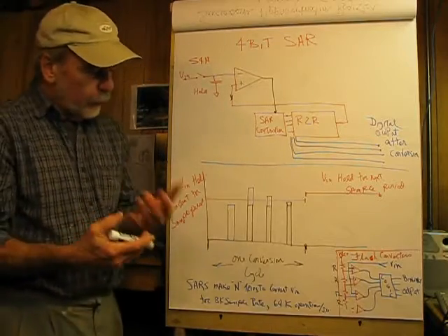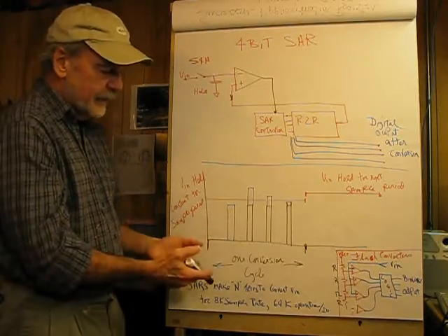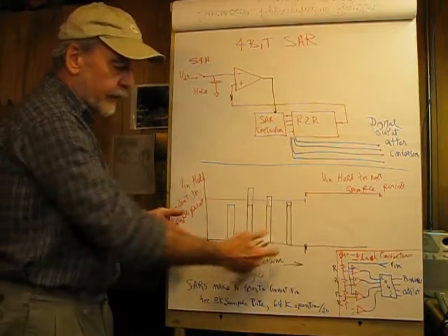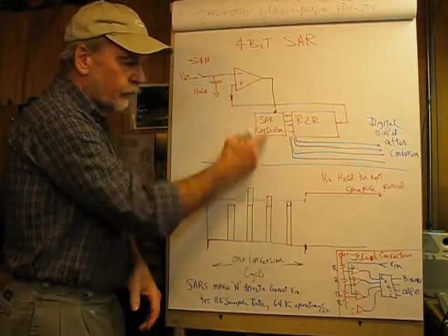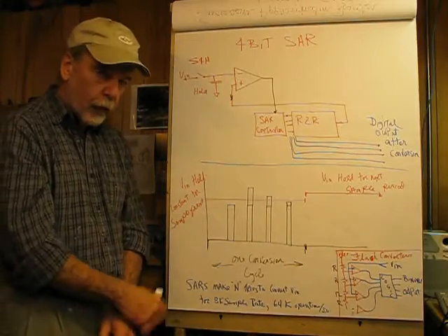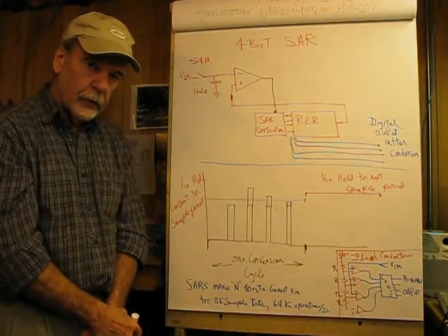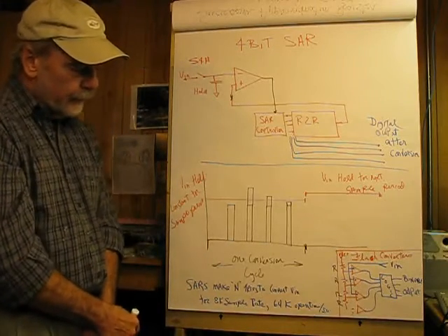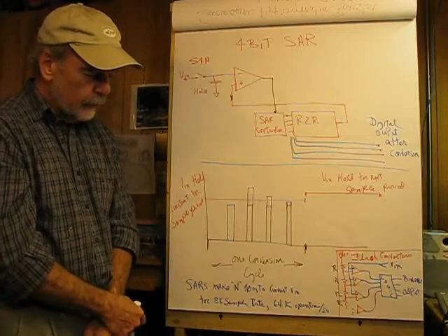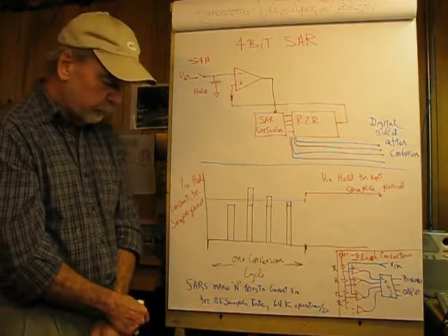So if we had an 8-bit SAR analog to digital converter, we could find the output in 8 iterations of the SAR controller as opposed to 64 up counts with the stair-step generator. So as you can see, the successive approximation approach is significantly faster.